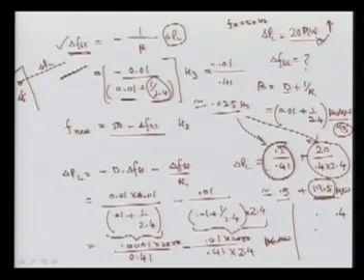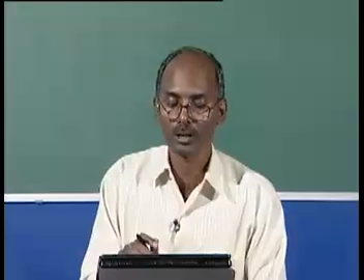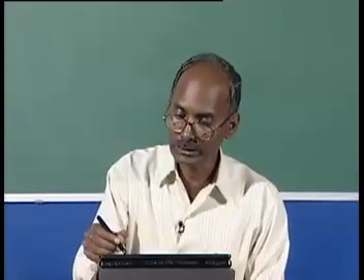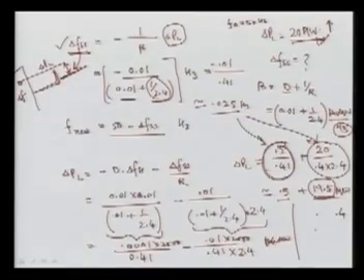The dynamic nature during the time constants we are unable to see, and by that we will see the dynamic response, but the steady state error exists here. So this is not sufficient, and for that we need a controller, because if the load is changed, we must not only supply this load, but we must also bring the frequency back to its normal value. So let us first see the dynamic response.